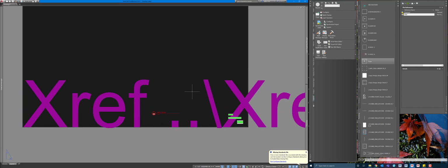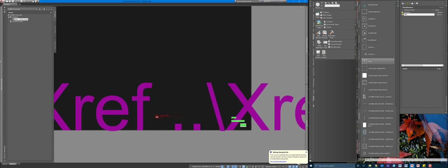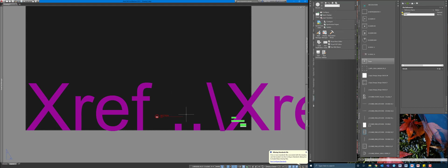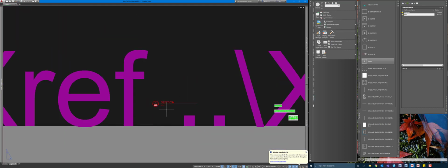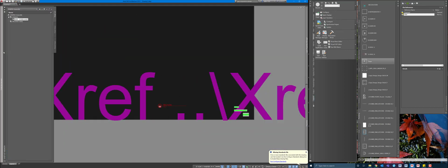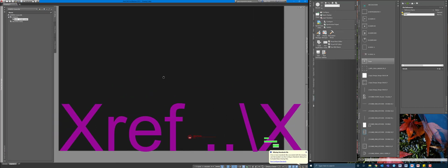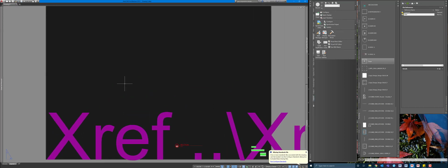But yeah, that's one of the main points of using a sheet set, right? Sheet sets allow you to organize your sheets in order and move them around. But because you have this sheet set information, if I right click and renumber a sheet that has 50 details on it, all these numbers that have fields will automatically update based on the sheet set. So it's an efficiency and accuracy benefit, right?